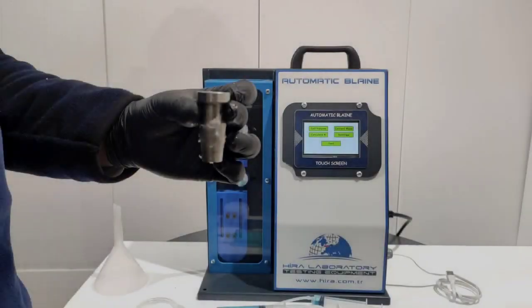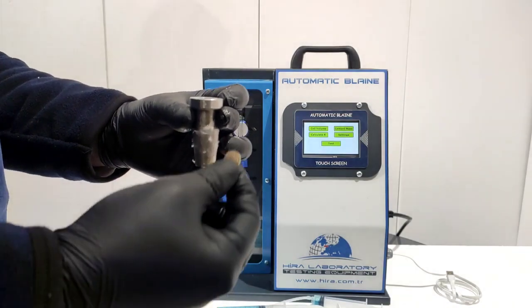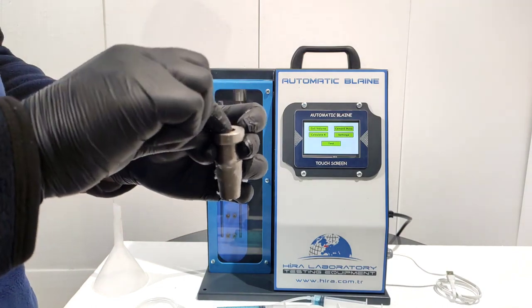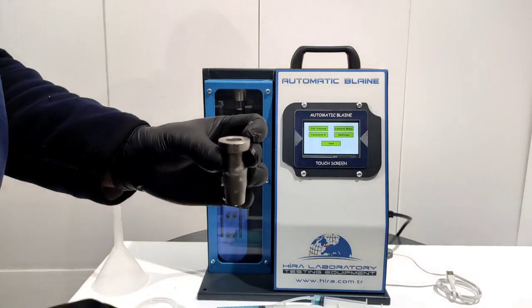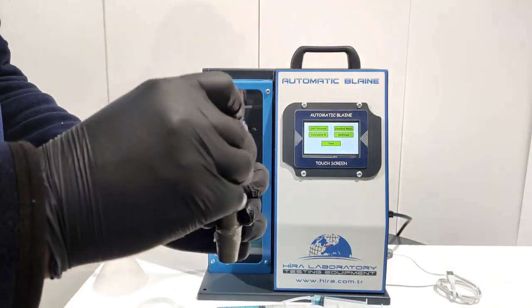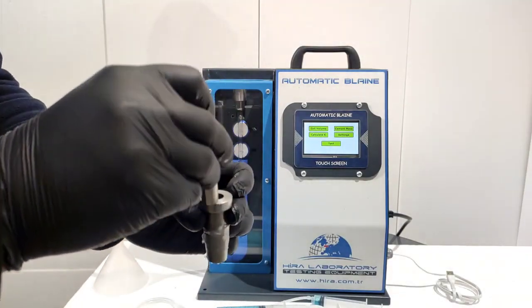The device should now be calibrated. Gently shake the reference cement by tapping it with your fingers for 2 minutes. Lubricate the cell surface with grease to prevent airflow along the cell surface. Put a perforated disc in the cell and tamp it with the rammer. Put a filter in the cell and tamp it with the rammer.